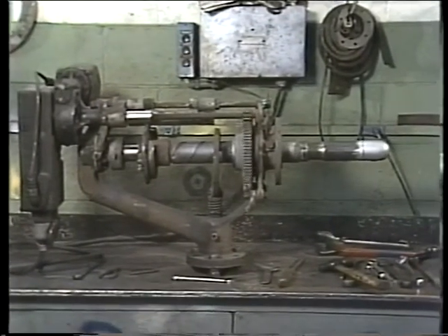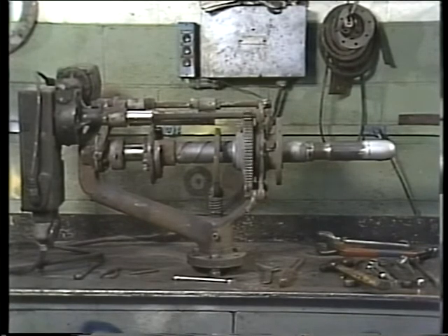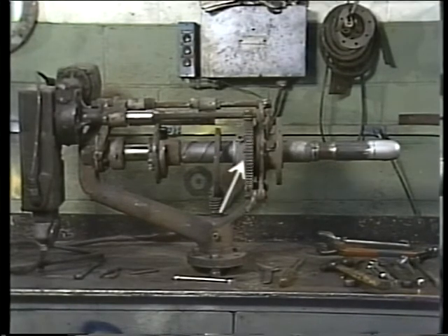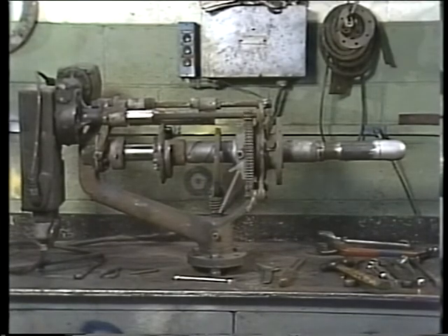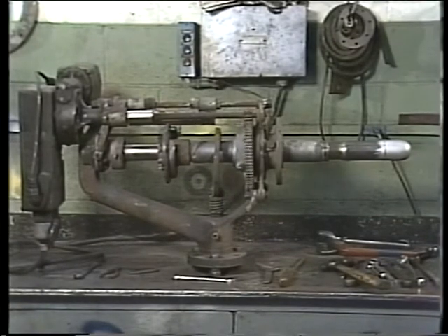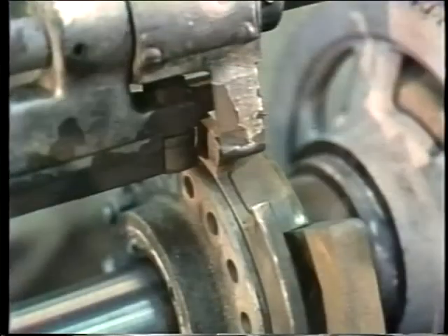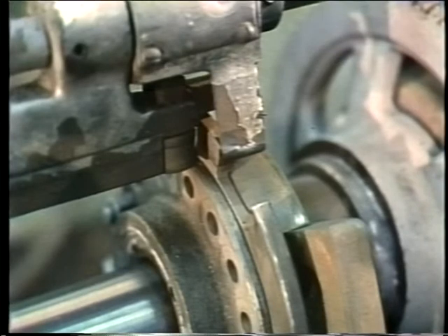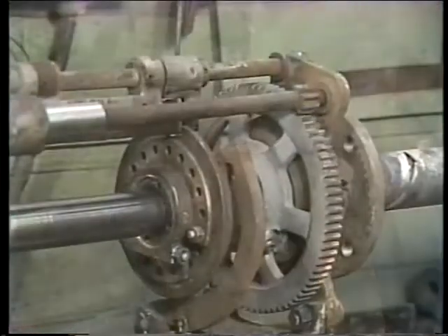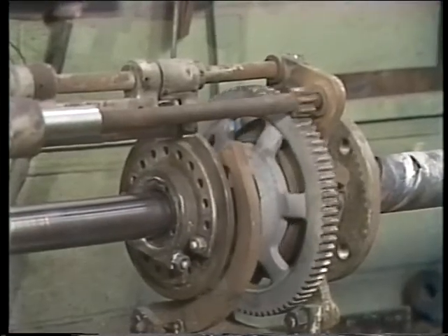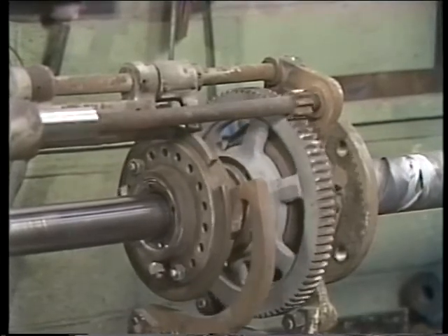As the drive gear turns, the element is driven outward. The pins that ride inside this collar act on the spiral grooves in the tube a lot like a screw that's driven into a piece of metal or wood. Notice the slot or notch cut into the cam ring and how it rides on the cam guide. When the element reaches the end of its travel, the cam is released by the pawl and starts to turn with the drive gear. The cam ring is mounted on the element, so the element turns also. As the cam starts to turn, it catches the valve trigger and opens the valve.